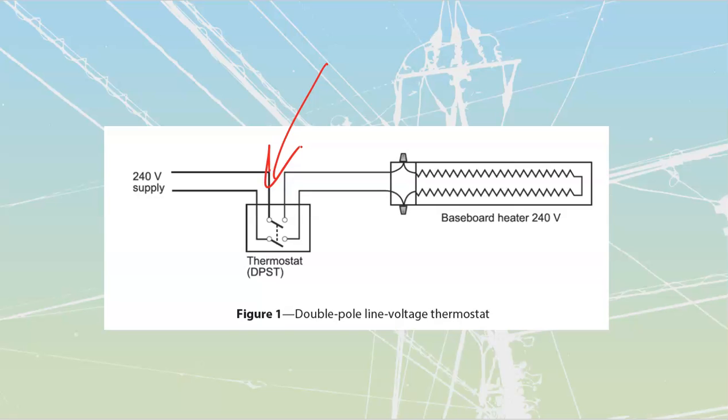It responds to temperature, and it can either be a normally closed thermostat that is going to go and open, or a normally open thermostat that is going to go and close. We refer to these as heating or as cooling types of thermostats. A cooling type of thermostat is going to close as the temperature would go and rise. We would draw that one out to look like this. This is our standard symbology for a thermostat. And a heating one would look like this over here.